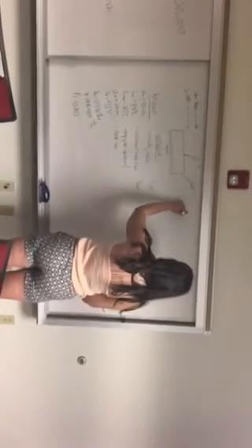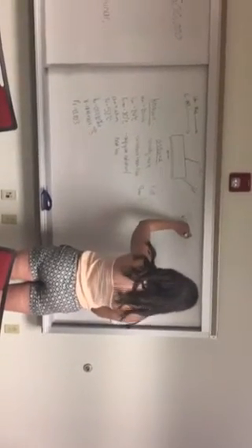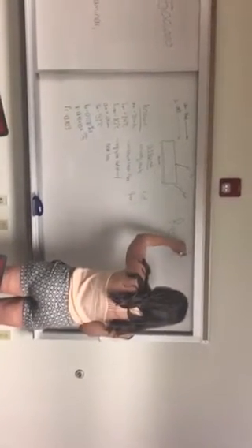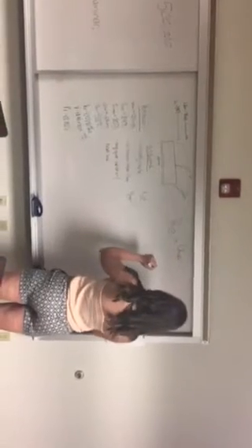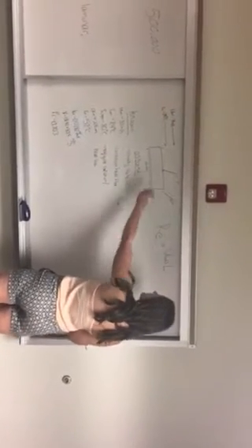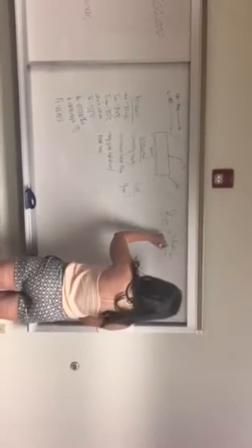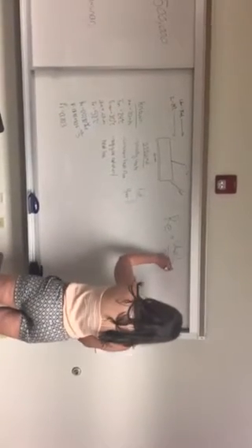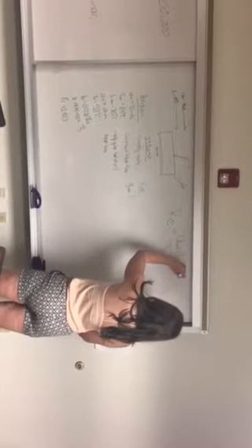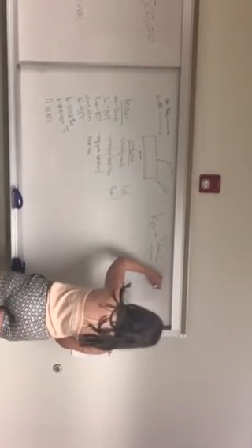We're going to start off by finding Reynolds number. So we do Re equals U infinity, which is our velocity, times the length, which is 10 millimeters or 0.01 meters, over nu. We plug in our numbers, and we have 20 meters per second.